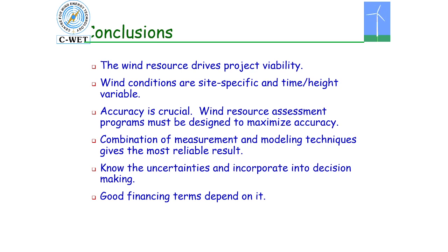You can use the generation data and the wind data available there, without putting up a wind mast, to assess the new scope of the repowered wind farm. Is it clear, sir? Any doubt on that?